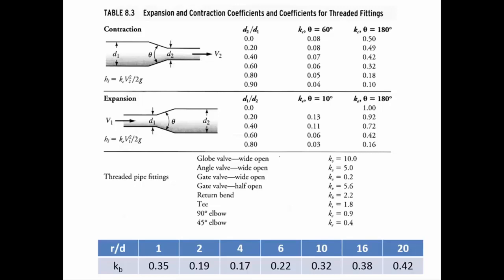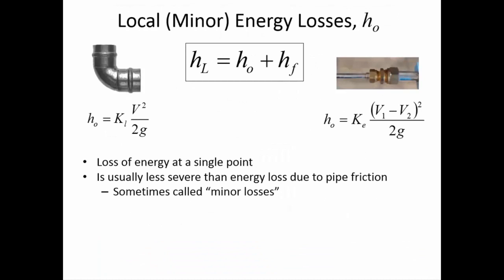We have the case of water coming out of a tank, and what it's showing is if you have an infinitely large origin and a small pipe, that's sort of like that top row there where it's saying 0.5. So what they're saying is that when you have water coming in from a tank to a pipe, then the K value is 0.5, and then you take that K value and multiply it by the velocity head, v squared divided by 2g. So whatever the velocity is through the pipe, even as the water is going into that pipe, it would be 0.5 times v squared divided by 2g.